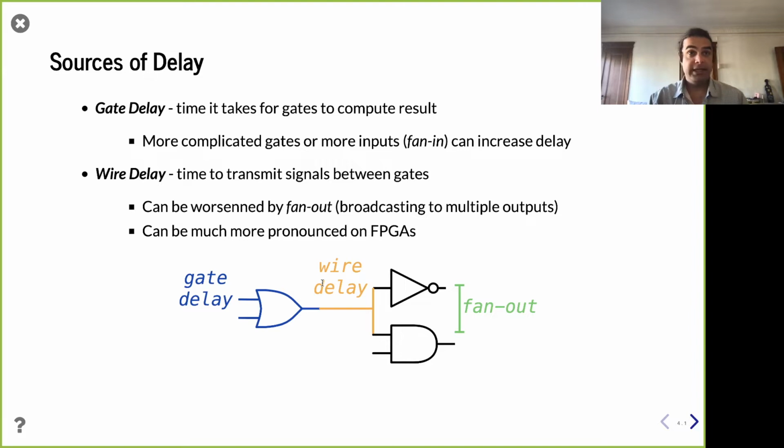Now, if you're on an FPGA, even if you're trying to go local, the routing delay, the wiring delay is much, much more pronounced, right? So sometimes the majority of the delay in the critical path in an FPGA is probably due to wire delay, right? So placement really matters. Understand, FPGA, of course, is able to reconfigure itself. There's some amount of extra capacitance and loads to charge and discharge, and longer routes it needs to go to avoid things or to reach other resources. So wiring delay is perhaps more of a concern for FPGAs, but both delays matter in both target technologies.